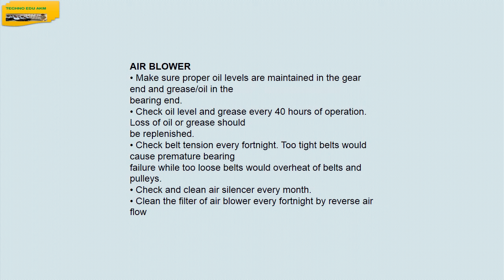Check and clean air silencers every month. Clean the filter of the air blower every fortnight by reverse airflow.